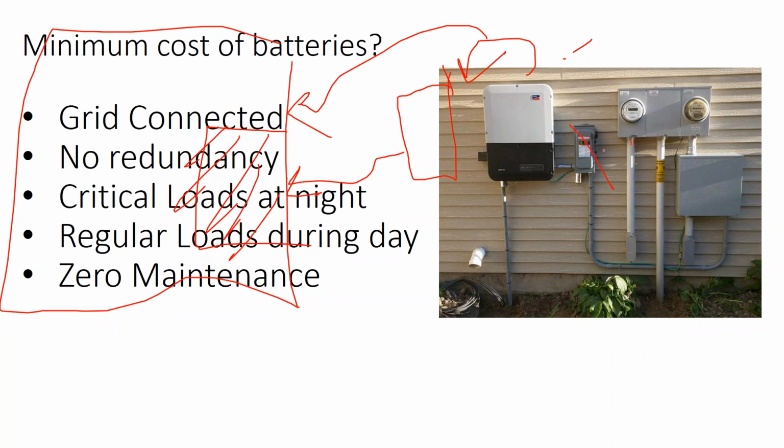And then down the road, this knife switch disconnect might go away. We might keep this box, but in addition to landing a battery inverter, we need to have the space to land our electric service panel. Most installers, when they're speccing out a job, are only looking for about 3 feet to land the solar inverter. You might want to make it more like 9 feet of space to be able to land an inverter, a battery inverter, and a service panel.